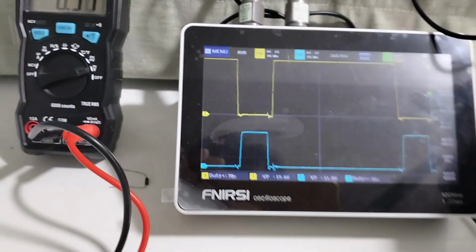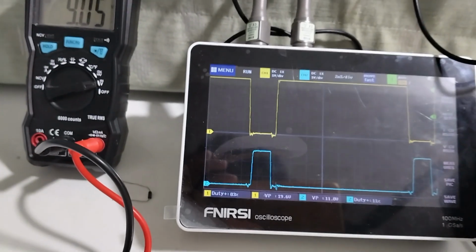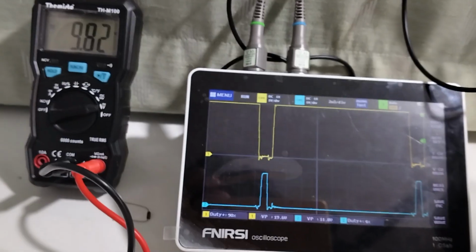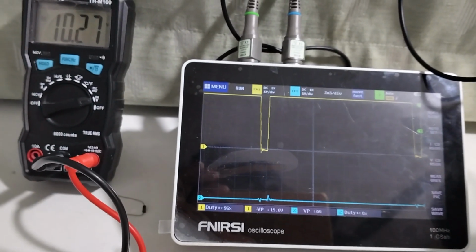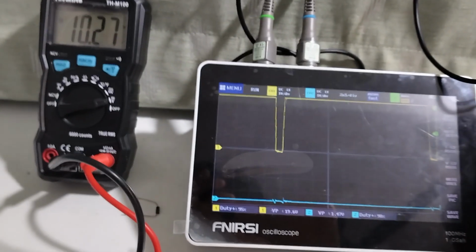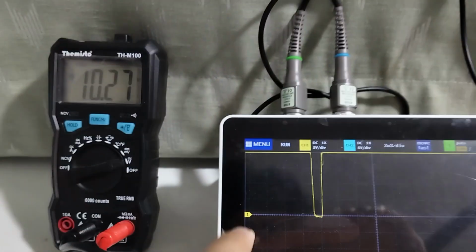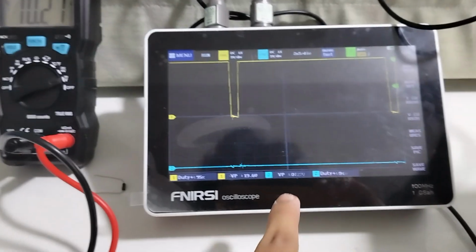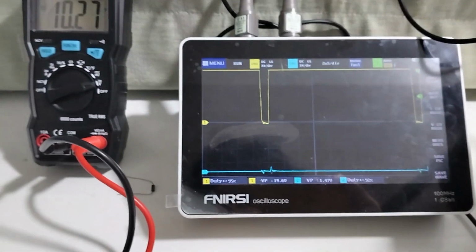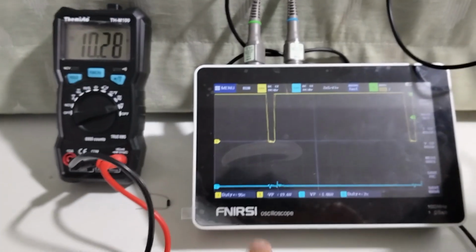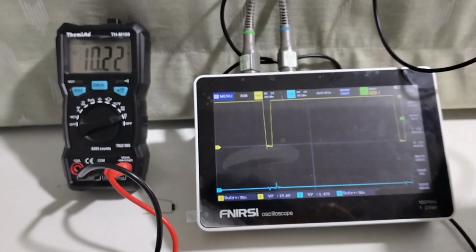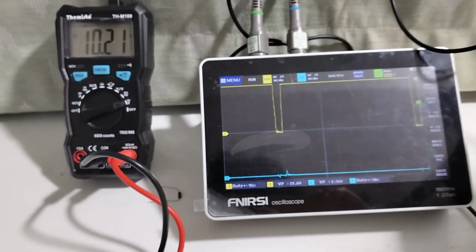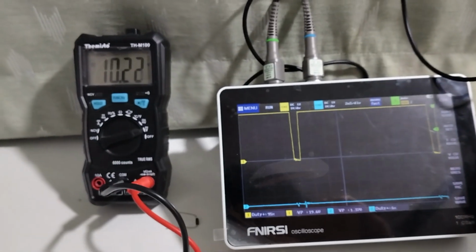So let's maybe take it to 85, 90, and maybe we can go up to 95. Of course you can go up to 100 itself. That is just going to give you your input voltage. But now you can see this thing is practically zero, because do know that in the lookup table which we have made, if you give too much dead time, there is some problem too, because you're going to lose resolution of the PWM.